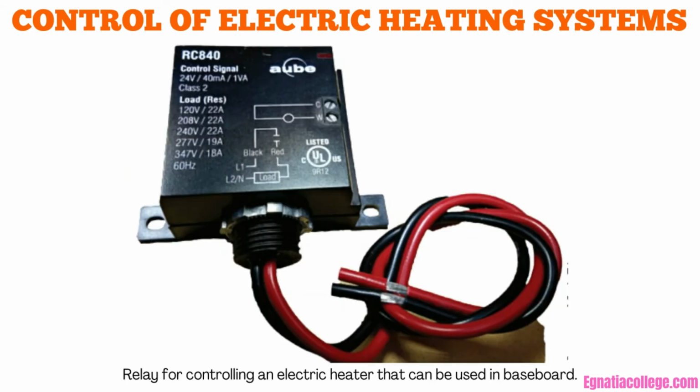When the connected load is larger than the maximum current rating of a thermostat and relay combination, the thermostat can be used to control a heavy-duty relay or contactor. An example of such a relay is the magnetic switch used for motor controls. The load side of the magnetic switch feeds a distribution panel containing as many 15 or 20 ampere circuits as needed for the connected load. A 40 ampere load may be divided into 3 15 ampere circuits and still be controlled by one thermostat. The proper overcurrent protection is obtained by dividing the 40 ampere load into several circuits having lower ratings.